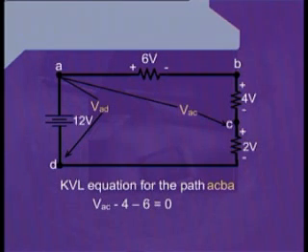As we are standing on the point C and looking onto the point B, we can see there is a resistance in between the points C and B, and the terminal of the resistance which is towards the point C has been marked as negative. Therefore, we will write minus there, and the voltage drop across this resistance has been given as 4 volts. Therefore, we write next to that negative sign 4. And we go through this circuit element and reach point B.